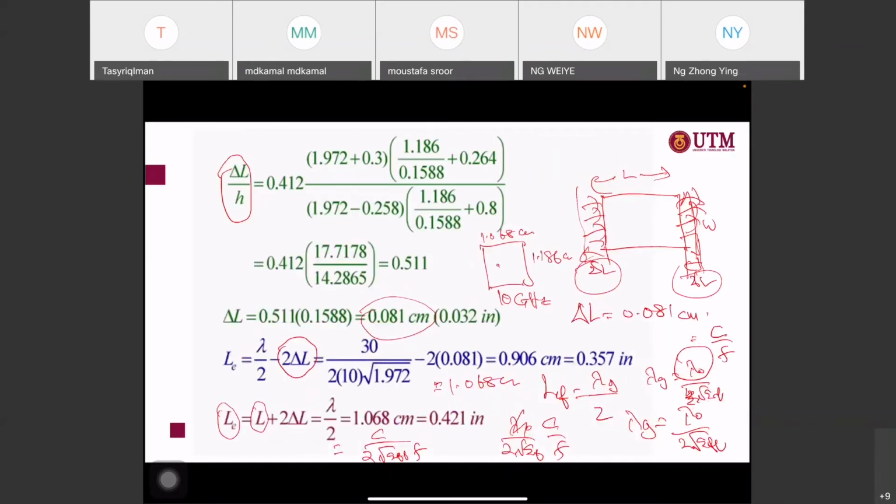So you know already your L and you know already the W. Once you design this patch antenna, we know that the antenna will be operating at 10 gigahertz. You can see the size of the patch is very, very small. All right, just a very quick exercise here.